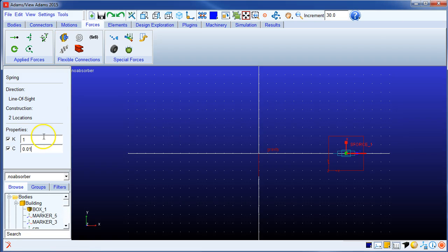If you want to put them in units, I'm not that good with units, but I think you put them in parentheses. Spring constant is a force per length, so I think LB for pound per inch would be reasonable. It doesn't like that, but look in the PDF file, maybe it's PLBF for pound force. Anyway, you can specify the units that you want. But if you don't specify the units, you get the default that you selected when you first started. Okay, so here's my spring.